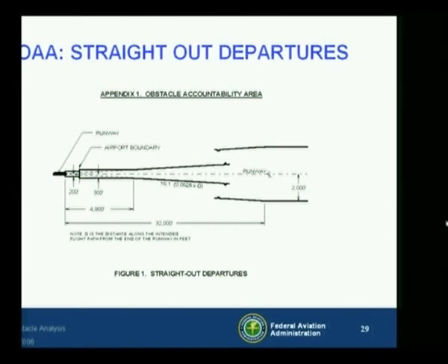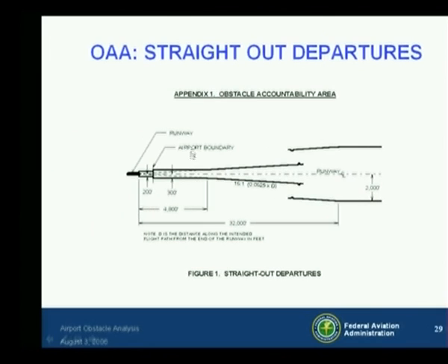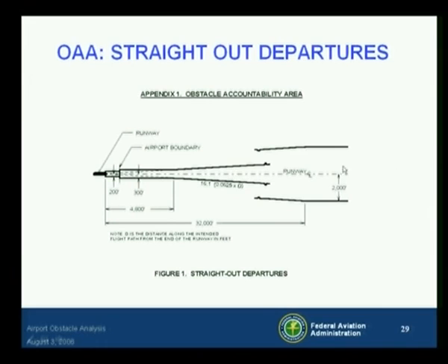Now, you see when we start at the runway here, the 200 and 300 feet corridor, if you will, is regulatory and controlling. Then at 4,800 feet, the 16-to-1 splay starts to widen out, actually meets the 300 feet edge of the corridor and begins to spread out. Now, the reason you have these splays anyhow is because as the airplane accelerates on the net flight path, it's going to need more obstacle clearance area because it's just simply going faster.